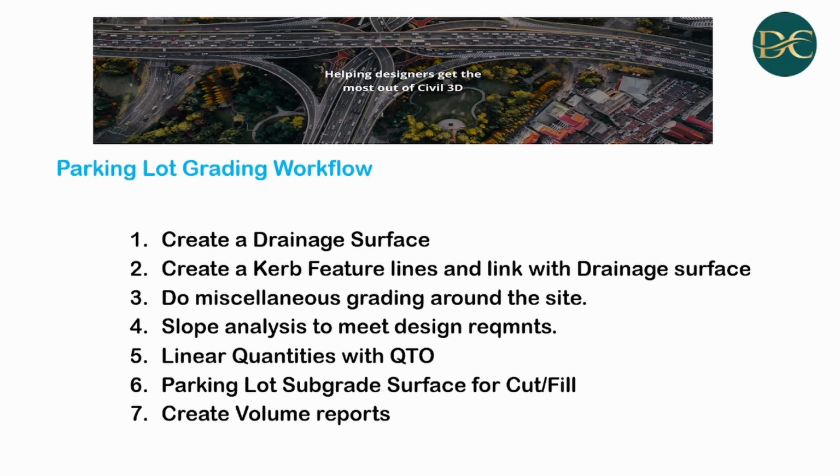The workflow we will follow today is that we will create a drainage surface. Then we will create kerb feature lines and link those with the drainage surface. We will then do some miscellaneous grading around the site. We will also do a slope analysis to ensure that the parking grading that we've done does meet the design requirements.